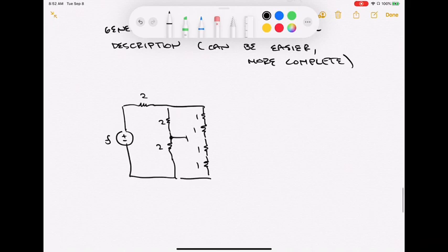And then I'm going to put a little capacitor, a 1 farad capacitor, in between there. And I'm going to look at the voltage across that 1 ohm resistor, and I'm going to call that V of t. Okay, if you analyze this, looking at the internal workings of the system, looking at all those circuit connections, what you end up getting is something like this. You get (8D + 1) acting on V equaling (2D + 1) acting on F, something like that.